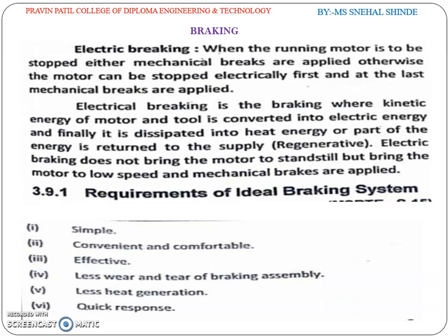Electrical braking is the braking where kinetic energy of motor and load is converted into electric energy, and finally it is dissipated as heat energy, or part of the energy is returned to the supply, which is regenerative.